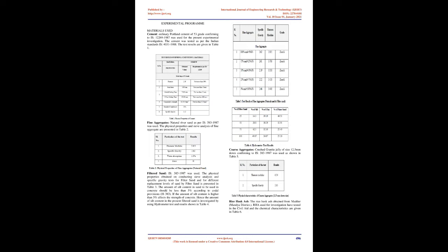The utilization of RHA as a pozzolanic material in cement and concrete provides several advantages, such as improved strength and durability properties, reduced materials cost due to cement savings, and environmental benefits related to the disposal of waste materials. The main components of concrete are cement, sand, and coarse aggregate. The production of cement adds pollution to the environment, a well-known fact to civil engineers. River sand, which is used as fine aggregate, is becoming very scarce. Sand mining is discouraged to save the rivers of our country.